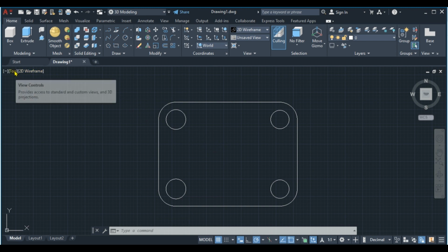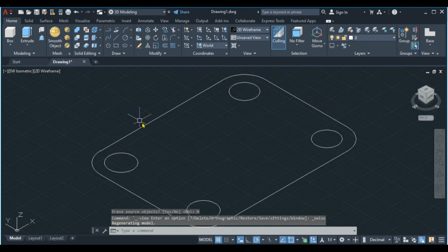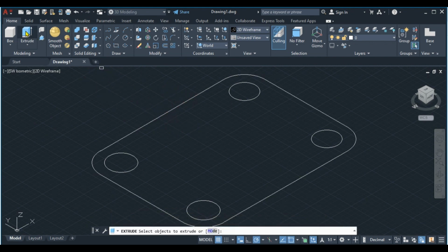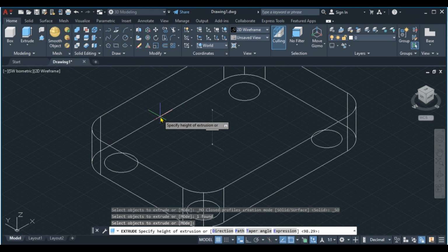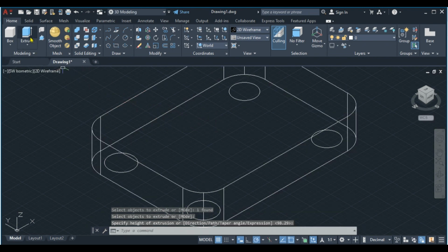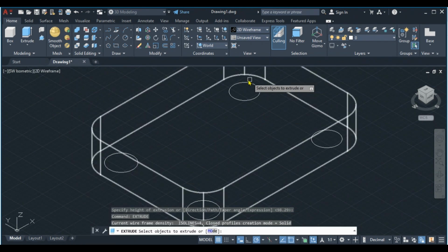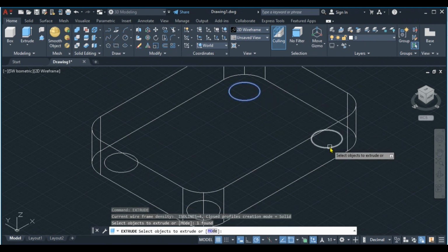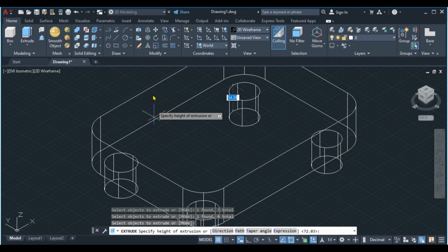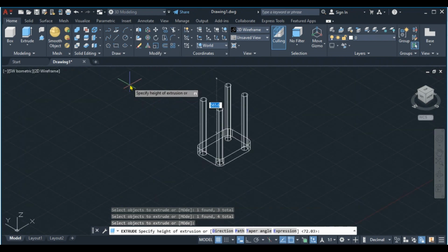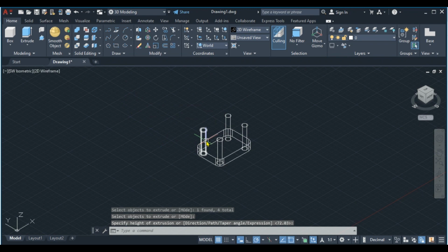All right. So let's switch to the 3D orientation and let's start modeling. So I'll come to the top here. I'll select the isometric orientation and I'm going to extrude. So select the extrude command, press enter. Then I'm going to extrude. Then I'm going to extrude again. Right. So right click, select extrude, and if possible, select these knobs. Okay. I'm going to extrude and press enter. And let's extrude them. Let's come up. I want to show you something. Let's come up like this orientation. This time around, the opposite.